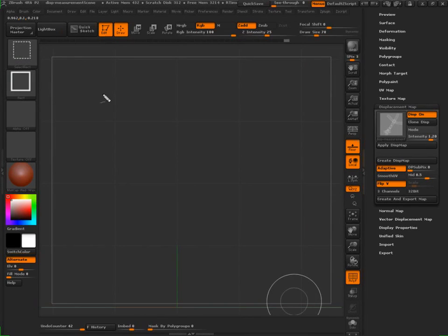So there are two types of displacement maps. One of them is called adaptive, and the other one is called not adaptive, which means adaptive is not on. The technical term, let's see, one was adaptive and the other one was, it's been so long I've forgotten, especially now that they've taken the name out. They take the name out, the memory goes with it. Anyways, DP subpix is only relevant if you're not using adaptive. Let me explain what adaptive does. And let me just explain what a displacement map does.